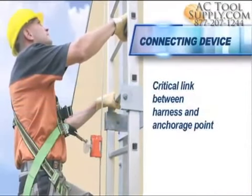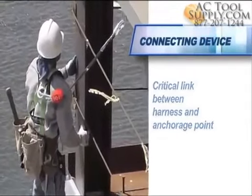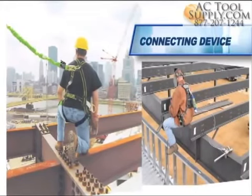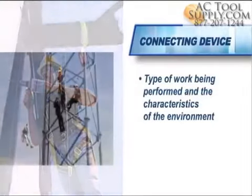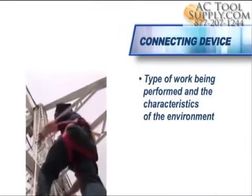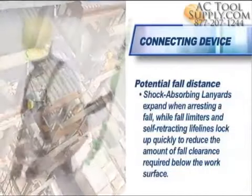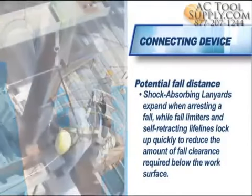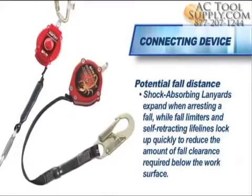A connecting device is the critical link between the harness and the anchorage point. The connecting device manages the greatest forces during a fall. Connecting devices should be selected according to these criteria: type of work being performed and the characteristics of the environment, such as the presence of moisture, dirt, oil, grease, and electric hazards, as well as the ambient temperature. Potential fall distance. Shock-absorbing lanyards expand when arresting a fall, while fall limiters and self-retracting lifelines lock up quickly to reduce the amount of fall clearance required below the work surface.